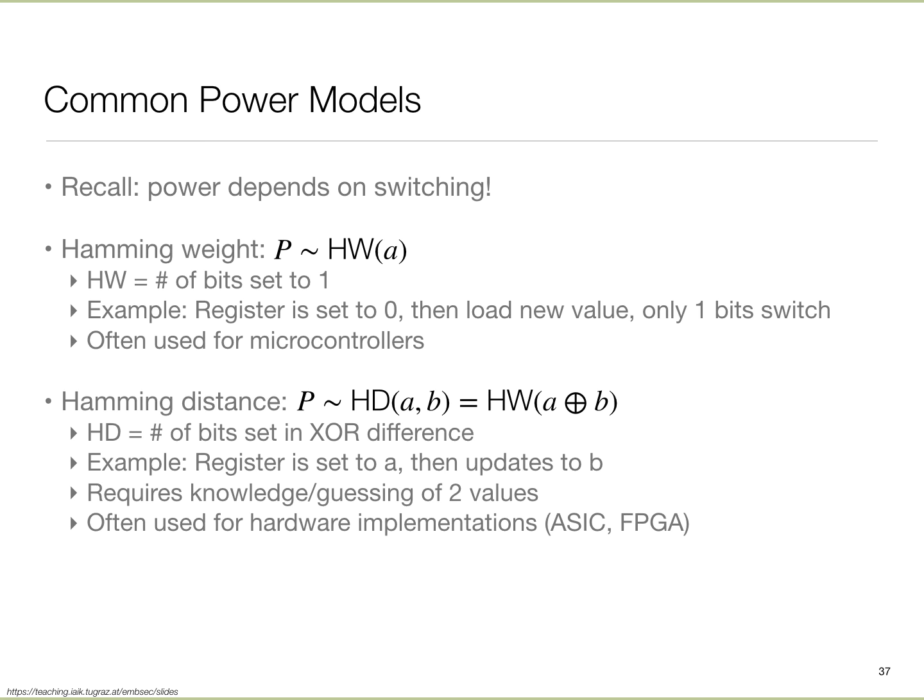And then there is a category of attacks called higher order differential power analysis. They get more sophisticated, but deep down your problem is that, given your knowledge of the device, the algorithm, and how the physics operates, you are given a time series, and you have to tell me what the value of the secret was when it ran. What would be the best match? What value of the secret will explain the observation that I'm seeing? That's really the problem that we are solving.